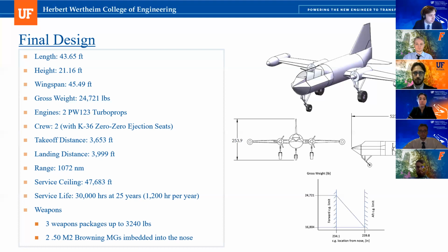And for the power plant design, from the initial estimation we have the thrust-weight ratio and the initial takeoff weight, so we know what the thrust required is, or for your aircraft probably the power-to-weight ratio. So what is the power required, right? And use that as guidance. So this is our engine, and this is the propeller, and this is everything in detail. And in the end, we can say that our engine can generate a certain power and thrust, and it does satisfy the requirements.